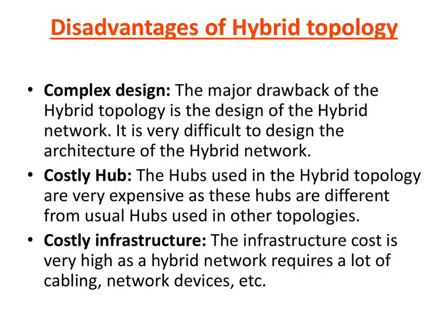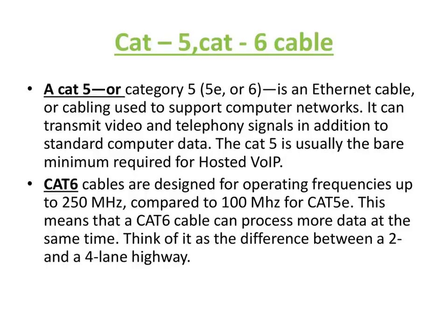T568A and T568B wiring standard basis. An RJ45 connector is a modular 8-position, 8-pin connector used for terminating CAT5E patch cable or CAT6 cable. A pinout is a specific arrangement of wires that dictate how the connector is terminated. There are two standards recognized by ANSI, TIA, and EIA for wiring Ethernet cables. The first is the T568A wiring standard and the second is T568B. T568B has surpassed 568A and is seen as the default wiring scheme for twisted pair structured cabling. If you are unsure of which to use, choose 568B.